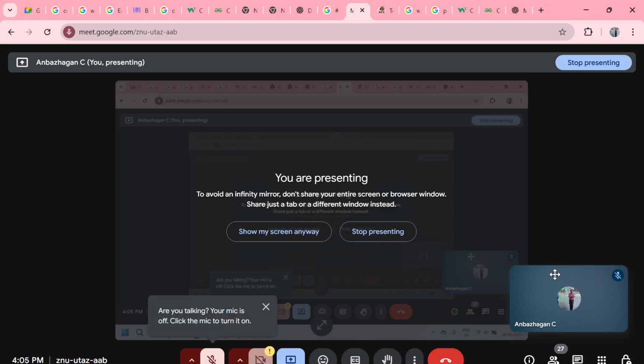Tell me, sir. If we declare a const variable globally, can we change it using pointers? No, you can't change it. We did the experiment itself, I think. Why? Any reasons? The reason is that it's flash memory. Flash memory is a read-only region, so you can't change that one.